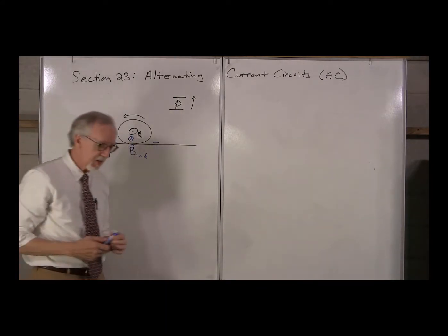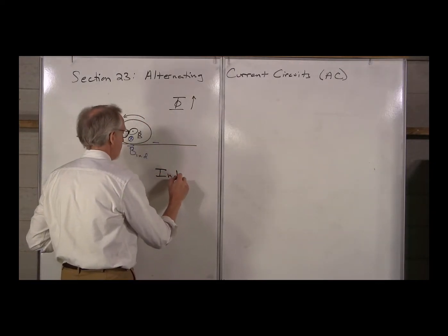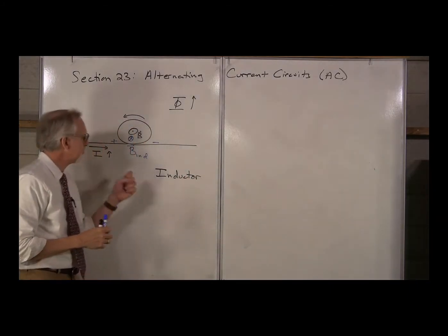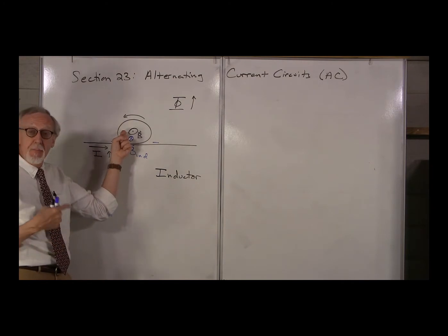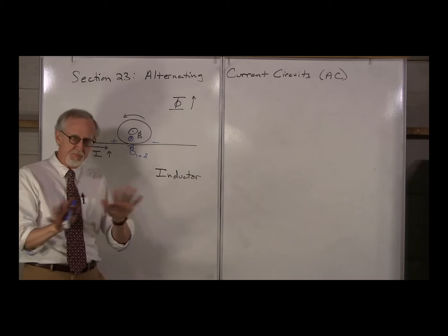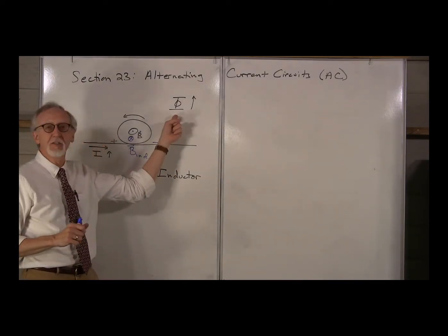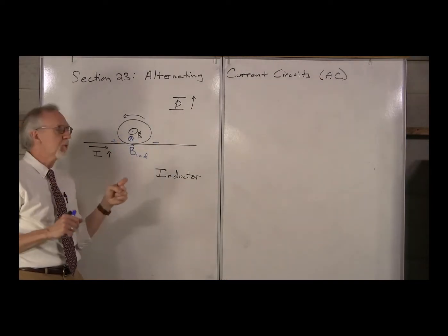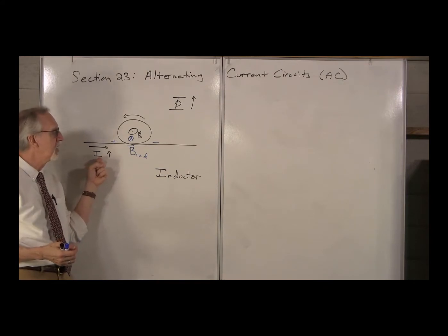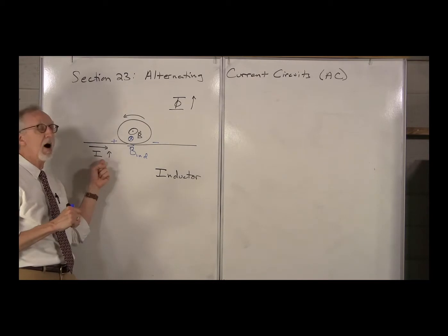And this circuit element is what we call an inductor. There is a magnetic field in the inductor due to the current, and that's fine, nothing happens. We don't have an EMF unless the flux starts to change. The flux will change only when the current starts to change. A changing current creates an EMF around the inductor to try and stop that change.